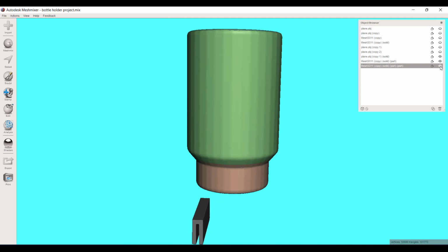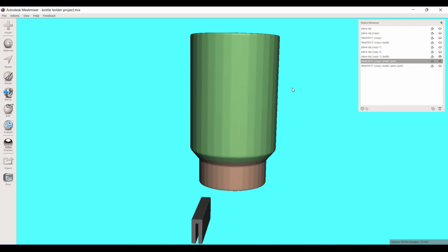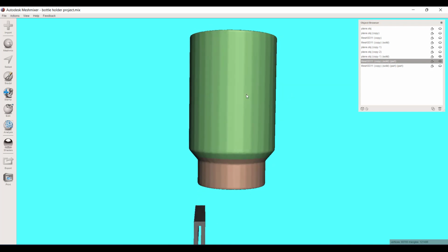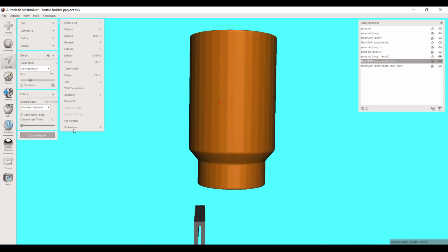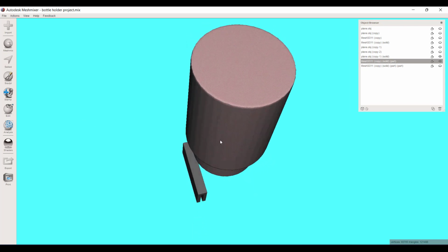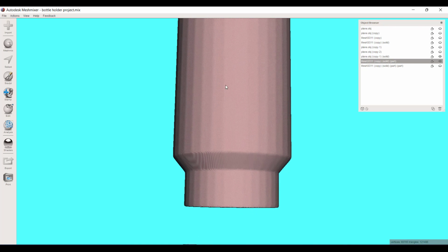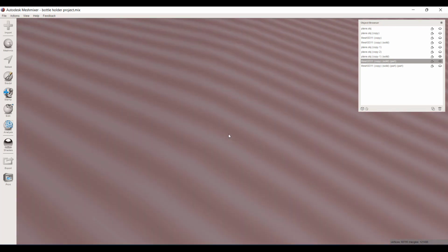But the problem with that is, if I turn this one off, both of these meshes are facing outward. All right. And in this scenario, I actually need this shape, Control A, to face inward. So I can just select it all and say flip normals. All right. That makes it this candy cane striped color, right? Because now, I wonder if I can go internal here.